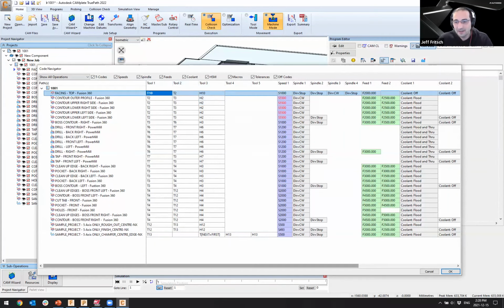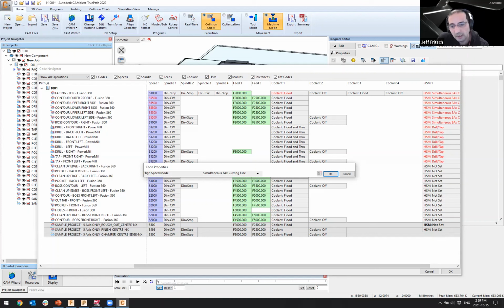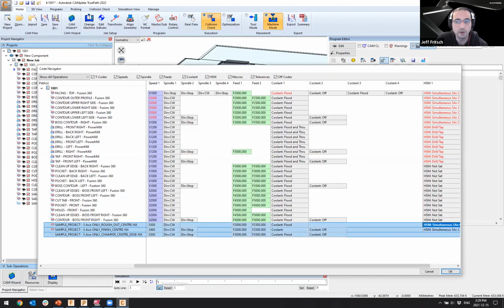So at the very beginning, we're really focusing on 3-axis roughing. So at that point, we really want to focus on having lots of horsepower driven through the tool, where the drilling and tapping operation will have a slightly different objective, which again is going to be completely different than the last few operations, which at that point are full-on 5-axis movements, which will again be completely different. At that point, we'll be looking at very accurate positioning, very defined movements, very smooth, no jerkiness. So completely different approach than the first couple operations, which are really plunging the tool into the material.